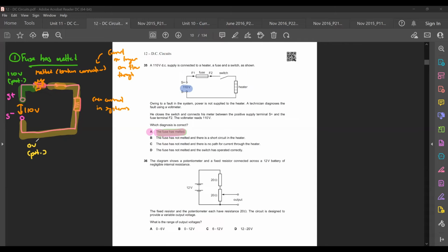Okay, remember I told you in 1 or 2 lessons before this, the value of electrical potential won't change unless your charge passes through a battery, where it gains electrical energy, so its electrical potential increases, or if it passes through a resistor, where it starts to lose electrical energy, so its electrical potential decreases. So in my case here, there's actually no charge flowing. No charge flowing through battery, no charge flowing through resistor. By right, there shouldn't be any changes in potential.